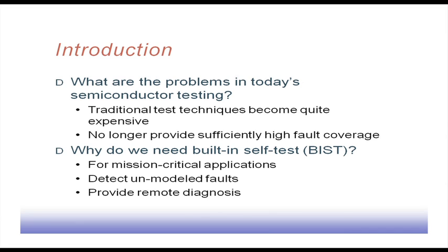So, to go back, what are the problems in today's semiconductor testing? Traditional test techniques become quite expensive. As we have seen, test pattern generation itself is a cumbersome process, and it requires a good algorithm to run, and it may require quite some time to generate the test patterns, and naturally to apply those test patterns. And at the same time, as the complexity of the circuit is increasing, it no longer provides sufficiently high fault coverage.